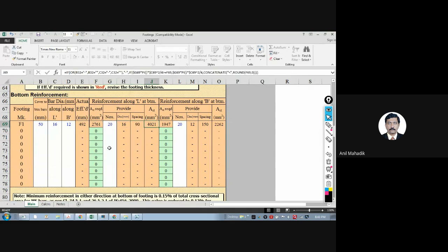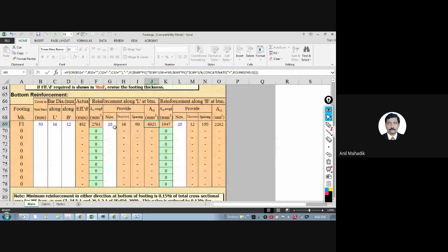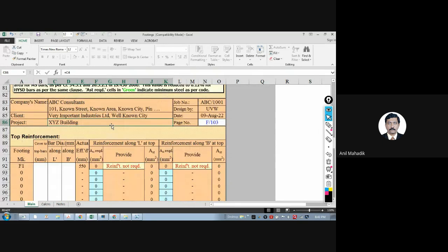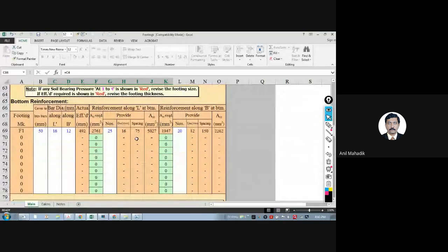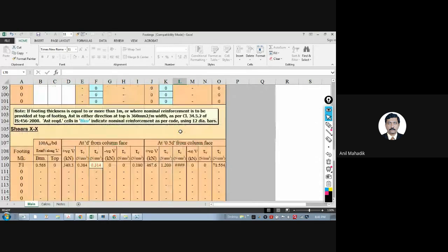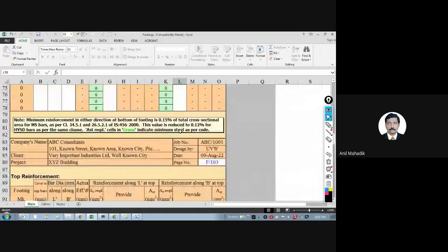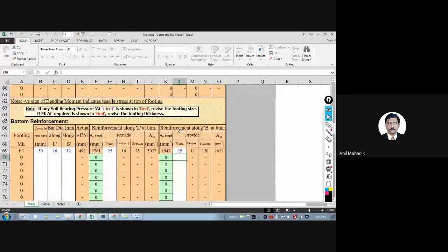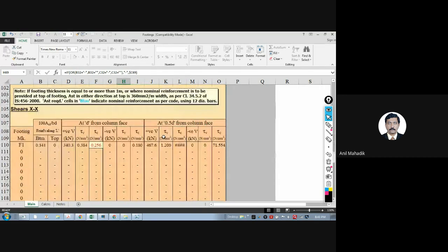Let's say this is 20. So based on shear stress, the depth, yes. Always, shear stress के लिए best option is depth ही है, क्योंकि steel बढ़ाने के बाद the footing will be very heavy, right? But yes, the cost will increase.